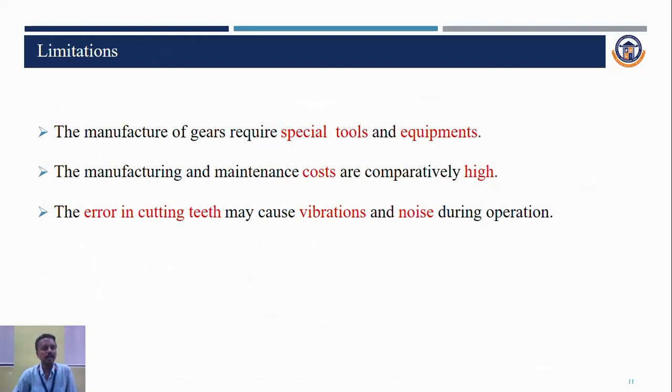Next one will be limitations of gears. The manufacture of gears requires special tools and equipment. Manufacturing and maintenance costs are comparatively high. The error in cutting teeth may cause vibrations and noise during operation.